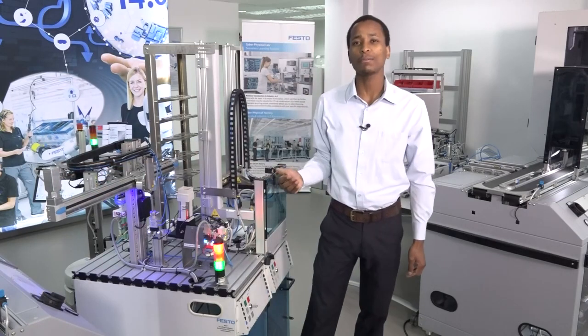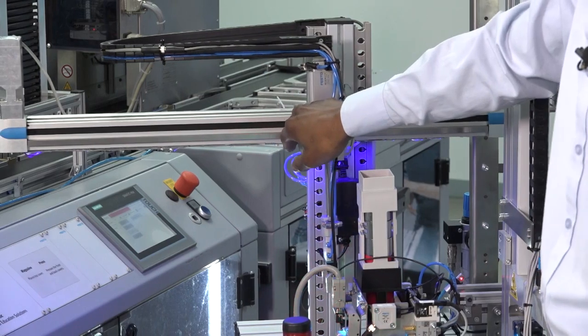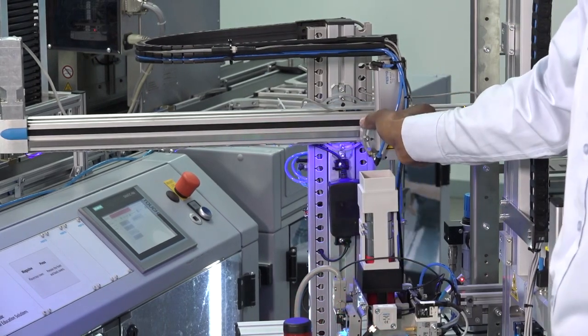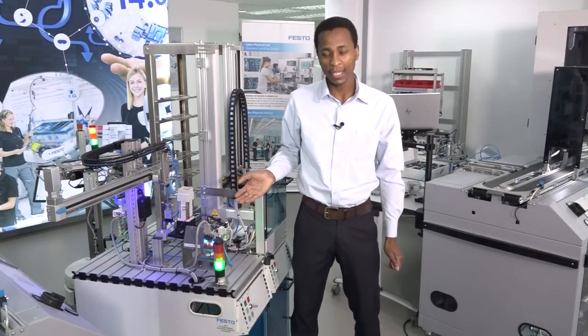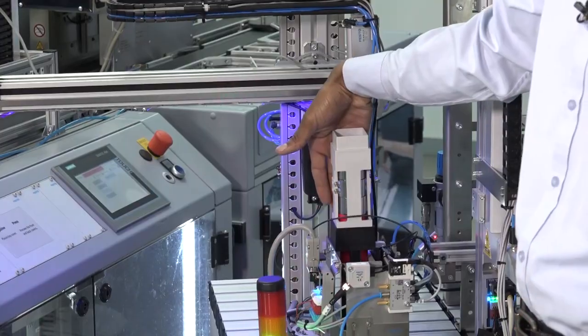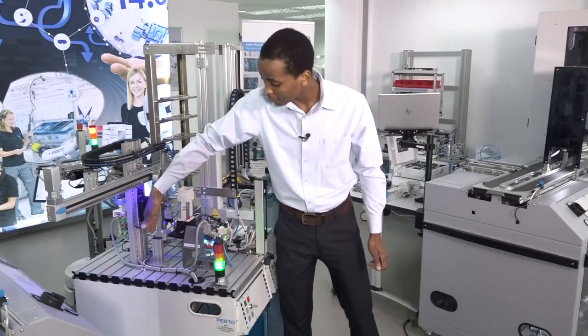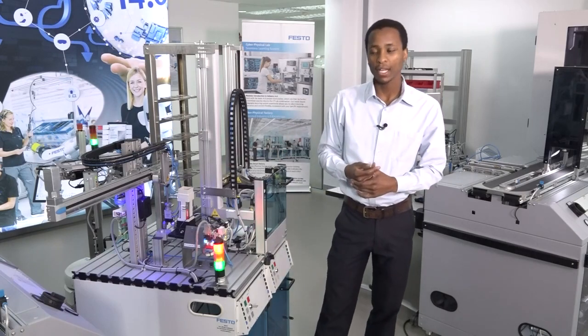And so we have a DC motor here. Sometimes instead of a DC motor, we use rodless cylinders that allow the control of both directions of motion, so forward and reverse or left and right. But this is a custom handling station. You can see that it has a magazine station here. So the magazine basically takes out a part and puts it onto this platform over here. That platform, we call it part available, so that when there's a part there, then the handling gripper unit will pick up that part and deliver it to the next station.